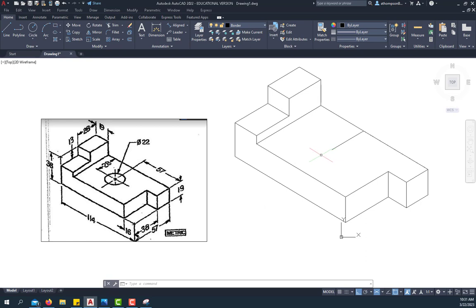And isometric circles can be created in AutoCAD. They're actually ellipses, but there is an option in AutoCAD that allows us to make an iso circle, is what it's called. For some reason, when you come up here to the ellipse command, it will not allow you to choose iso circle on that one.